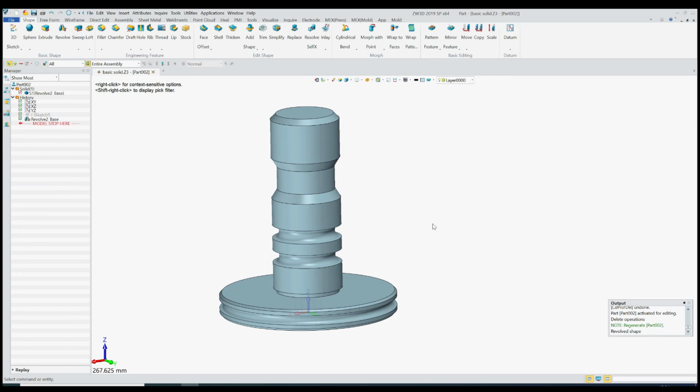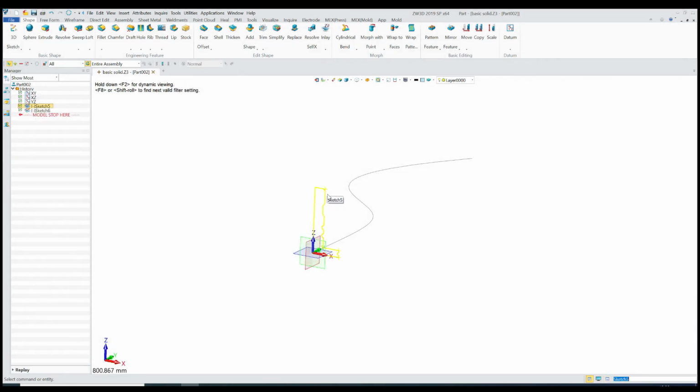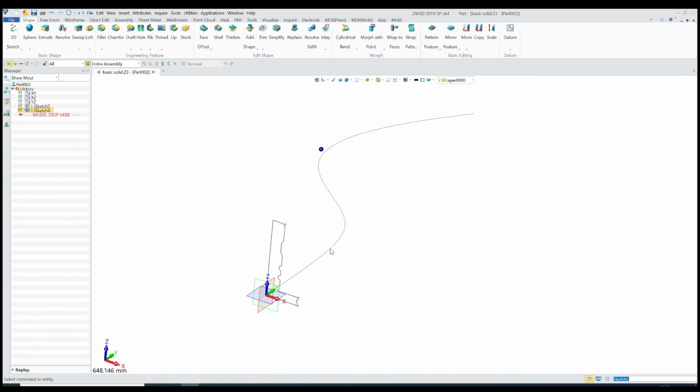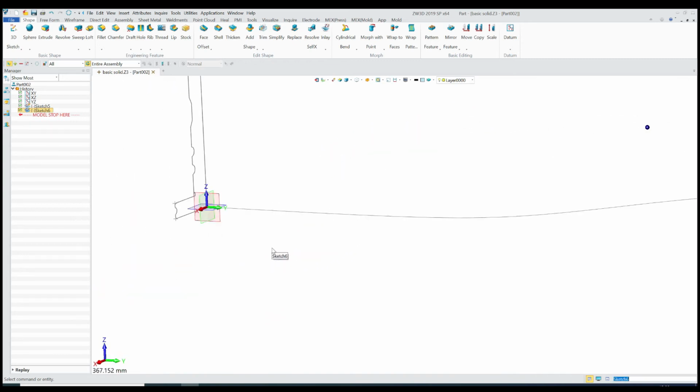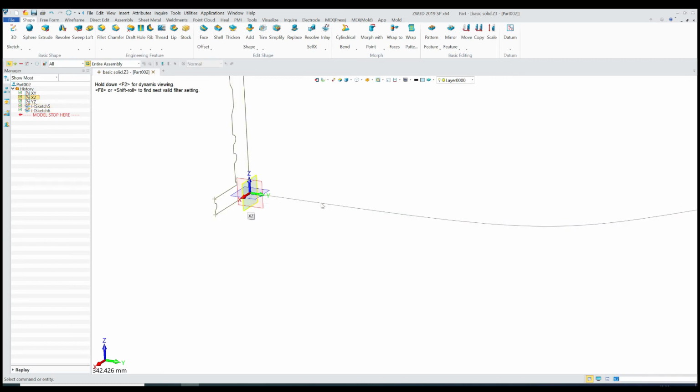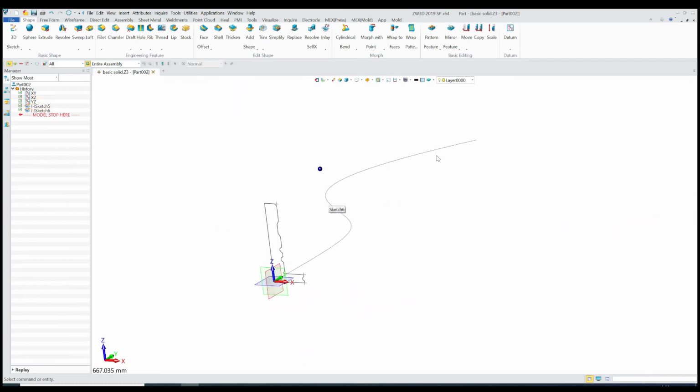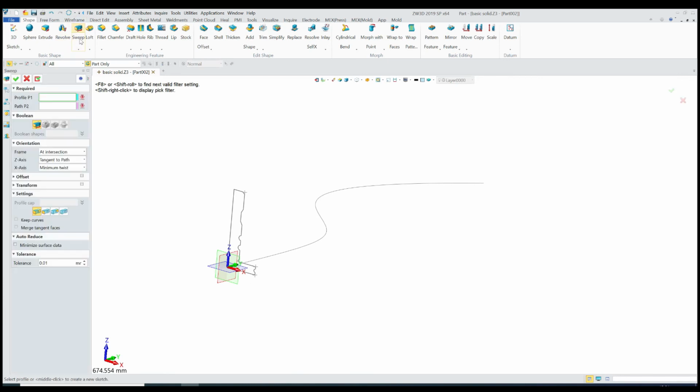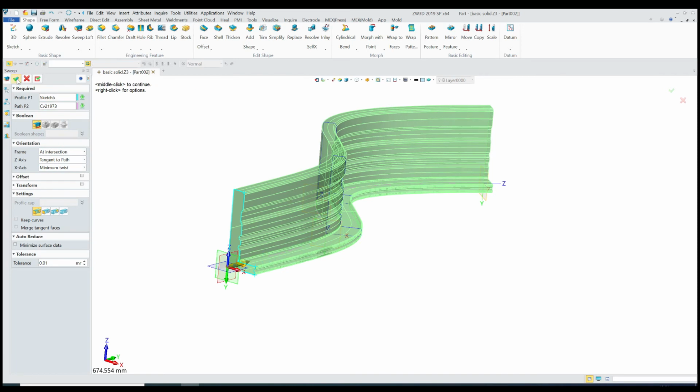Now this is a little bit different because we will be using two sketches. I'm gonna make the sketches and we go from there. So here we have our two sketches. As you can see, I have reused the sketch from the previous command, and I have the path here as well. You need those two sketches to make the sweep command. One thing to keep in mind is that both of the sketches need to connect to make this command possible. So let's choose the sweep command, and we can choose the contour and the path and confirm.